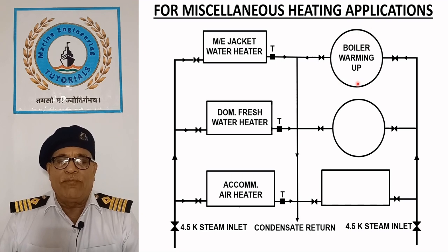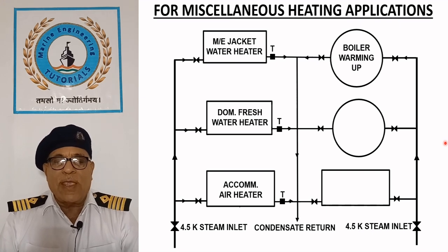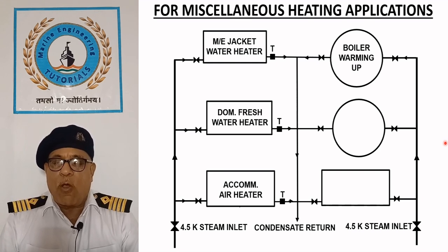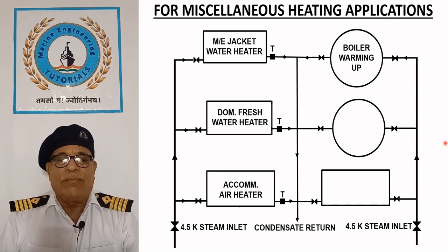Boiler warming up. When the auxiliary boiler and exhaust gas boilers are independent on motor ships, the auxiliary boiler is kept warm at sea and the exhaust gas boiler is kept warm in port using simmering steam.